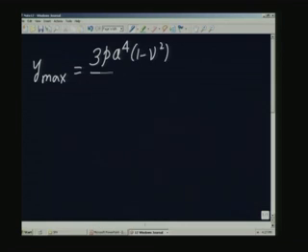And let us find out what will be the central deflection. You remember, the diaphragm is held fixed at the periphery, and therefore, it is going to bulge out, and the maximum deflection occurs at the center, and we are now talking about the central deflection, which is given by 3 p a to the power of 4 into 1 minus nu squared, which was already worked out, divided by 16 E t cube. This formula also was given earlier in the last lecture.